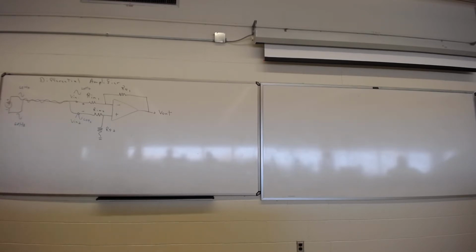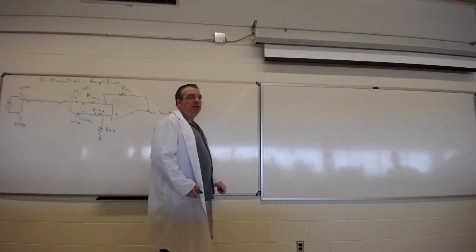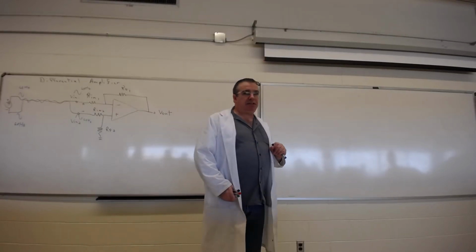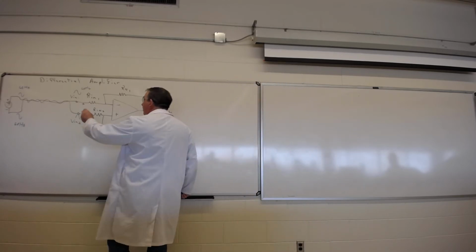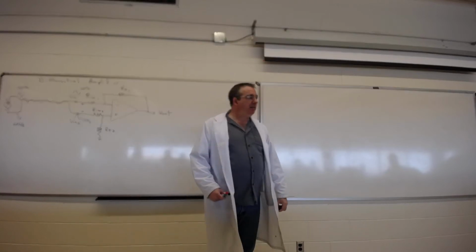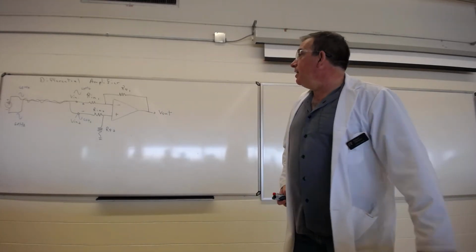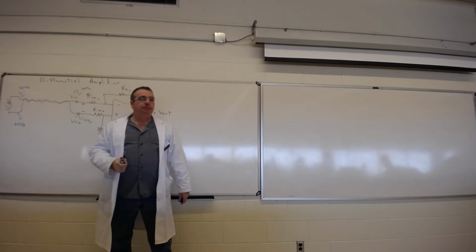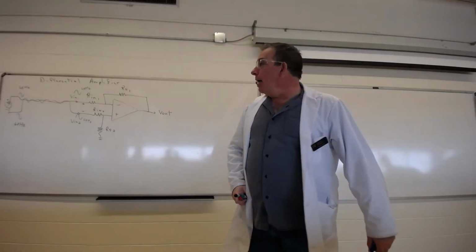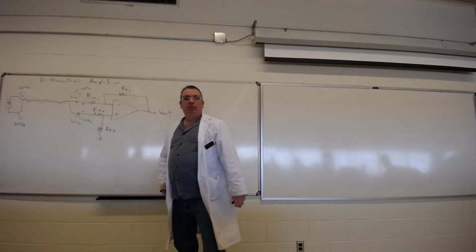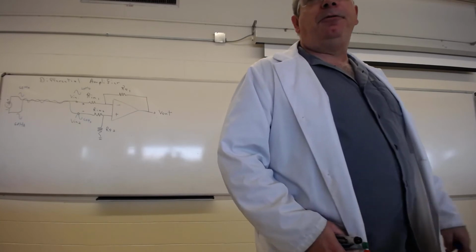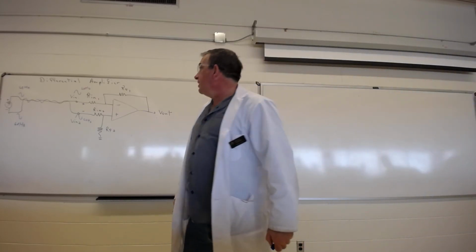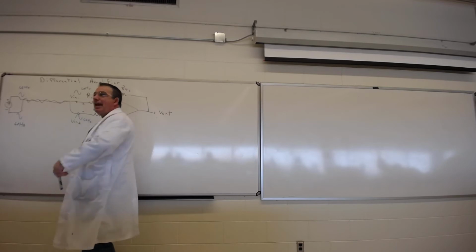That's not good. Now, here's the beauty of this little beast, this little op amp, why they built these things, is that it's made to amplify differences, okay? If it gets the same thing on its inputs, it won't amplify it. It cancels it out. So the whole idea with our differential amplifier is that when it sees the same kind of noise on both lines, it rejects it and will only amplify the differences. Okay? So a differential amplifier, what's nice about it, it'll take the voltage that's coming off the sensor, but whatever noise that's hopped on, that is common on both wires, gets canceled out.